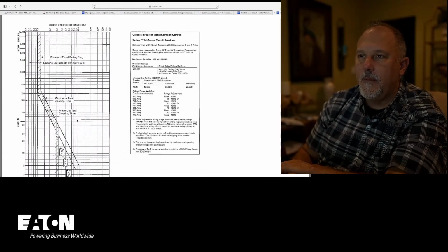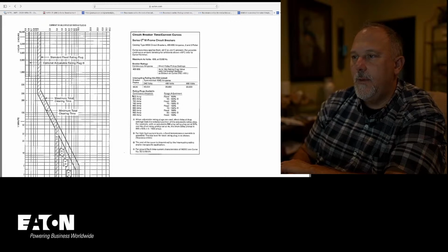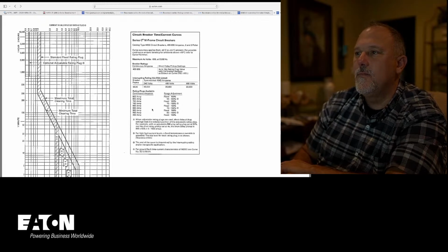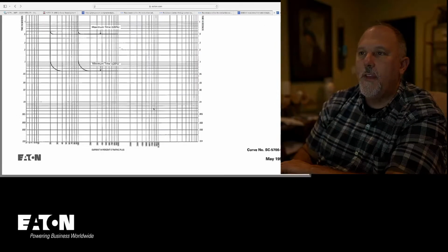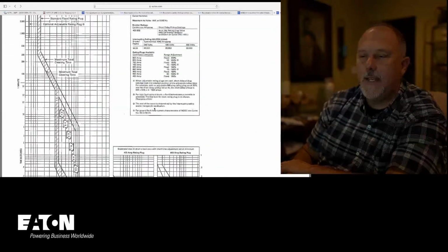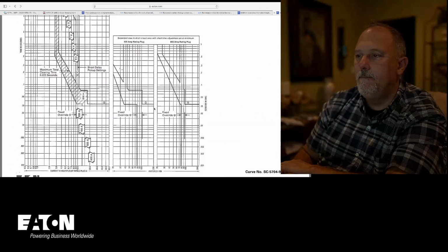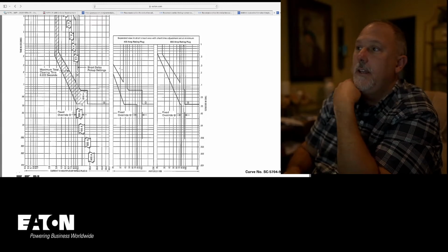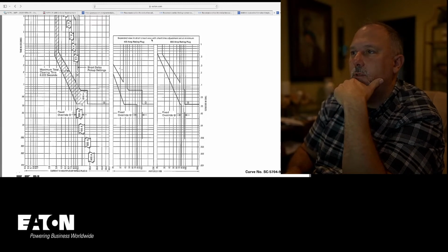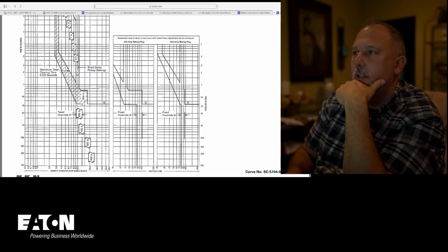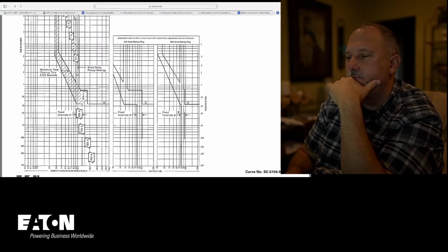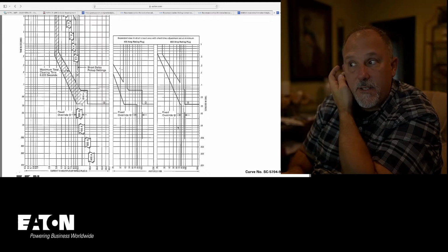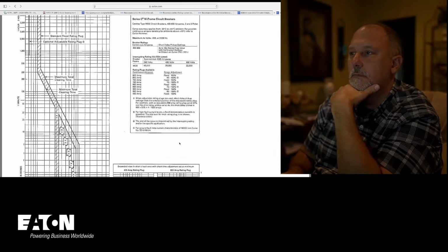400 to 800 amps. So here we go. Here's an 800 amp. That's still electronic trip unit. I want thermal mag. I don't think I can get a thermal mag in 800. All right, so here's my 800 amp expanded view in short circuit area with short time adjustments set at minimum. So there's my fixed override. That's around 9,000 amps.